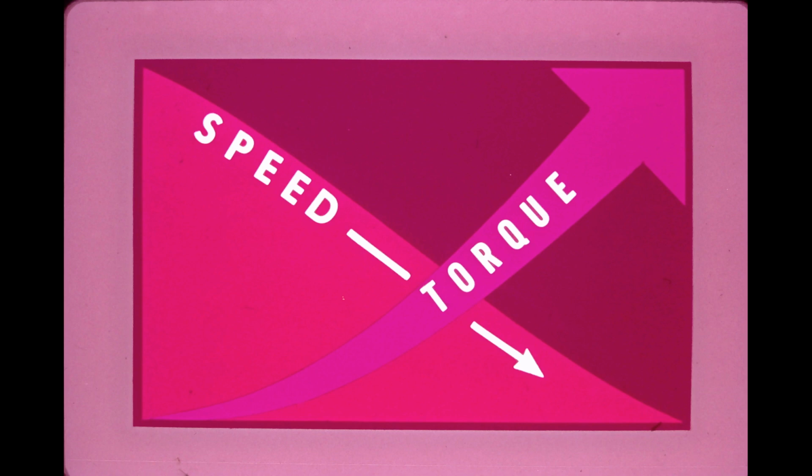But notice what has happened. In order for the payloader to develop the torque to climb the grade, speed was greatly reduced, even though the operator kept the machine at full throttle during the climb. This illustrates a fundamental principle for torque converter operation. Speed and torque are inversely proportional. This means a converter will not deliver both high speed and high torque at the same time. If a machine needs more torque than the engine can deliver, the torque converter will automatically supply the additional torque, but will do so at the expense of machine speed.